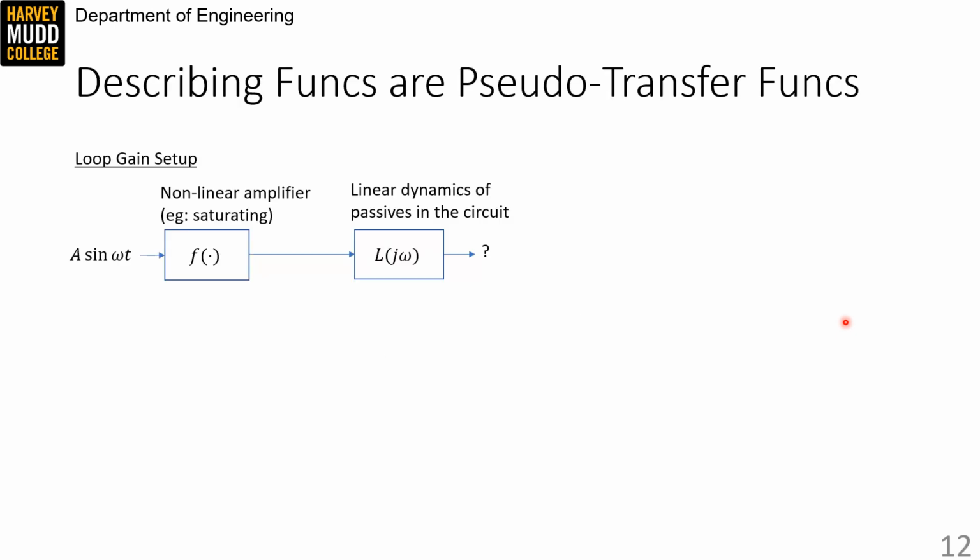We need to do describing function analysis because all practical oscillators are nonlinear. A linear system with two poles on the j-omega axis would oscillate forever if you kicked it with an impulse. But a second impulse would create another oscillation that's stacked on top of the first one. Further, there's no reason that a purely imaginary system would start up of its own accord and reach a big oscillation. Random thermal disturbances would be present and they'd stay forever, but they'd be small.